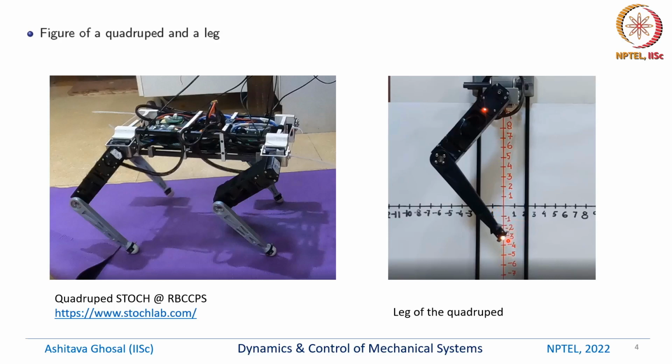What we want to show you is that this robot can go up and down. We want to control the motion along this red line. This is like the y-axis, this is like the x-axis. By controlling the current or the voltages going into the motor, we would like to ensure that the tip of this planar 2R goes along this vertical line.